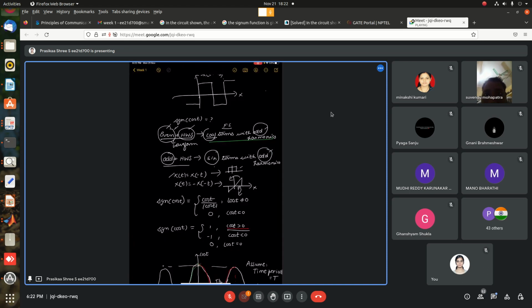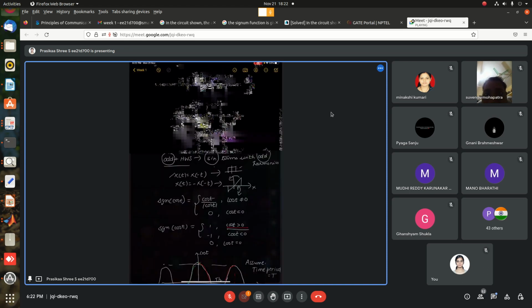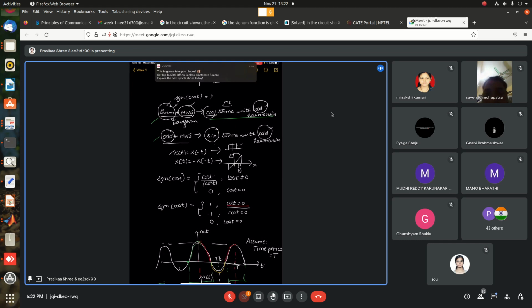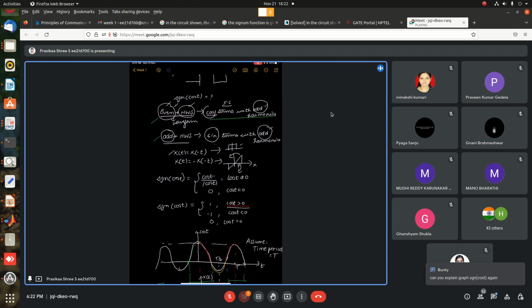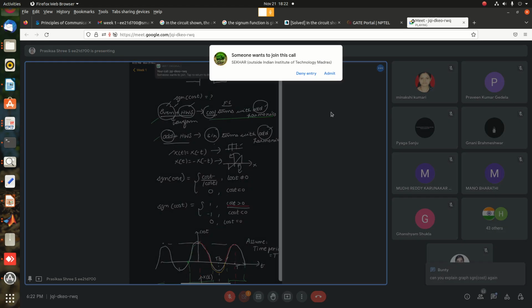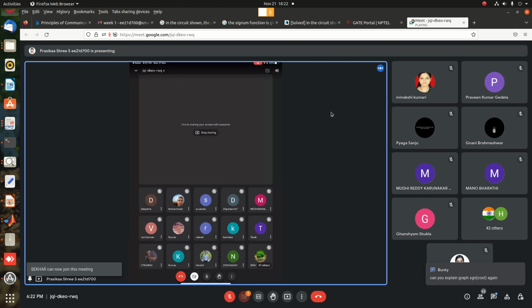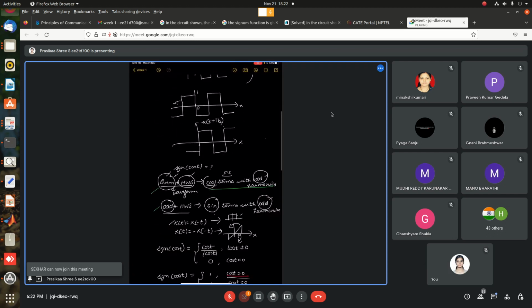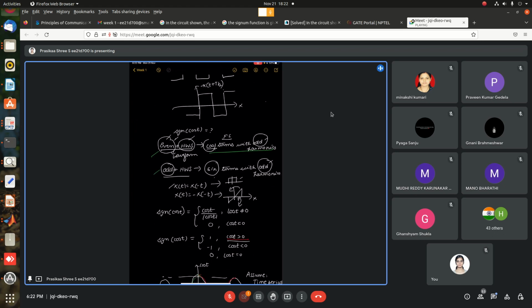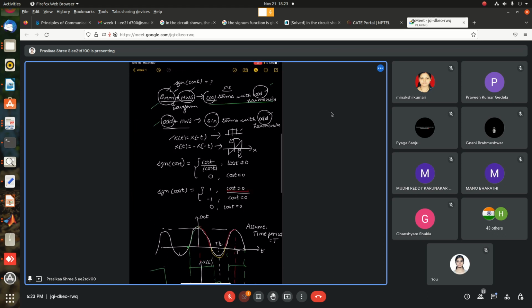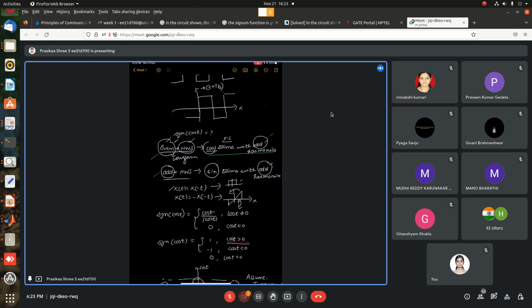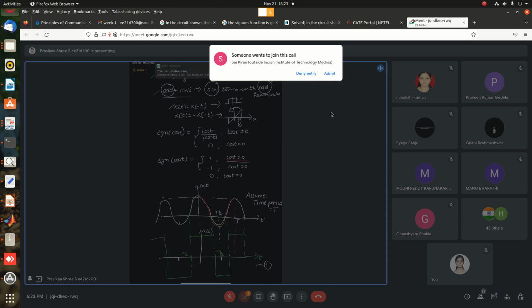Like these properties, if a signal is even plus HWS, or if it is odd and half wave symmetric, this Fourier series expansion will contain only cos terms, and sine terms can be derived. They can be derived and they can be solved. But as of now, I'm just giving a revision and a keynote such that you can solve the problems much more easily.